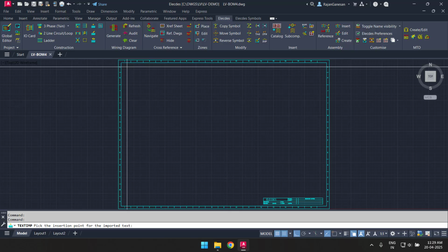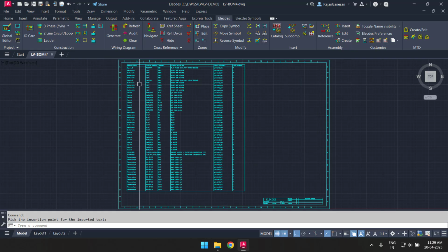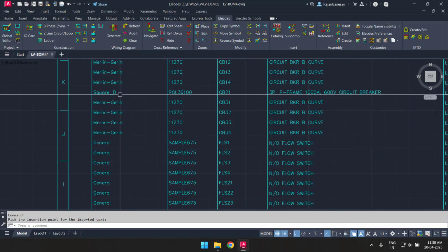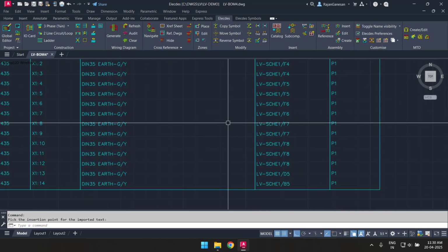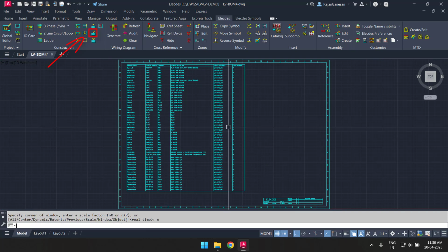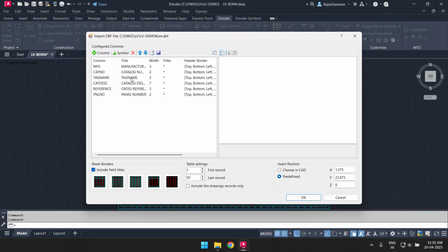The materials table is now drawn. The table is both adjustable and refreshable. By adjustable, I mean that I can edit the table at any time and adjust the contents, format, and layout of the table. To demonstrate adjustable, I will edit the table and increase the column width for the tag names.